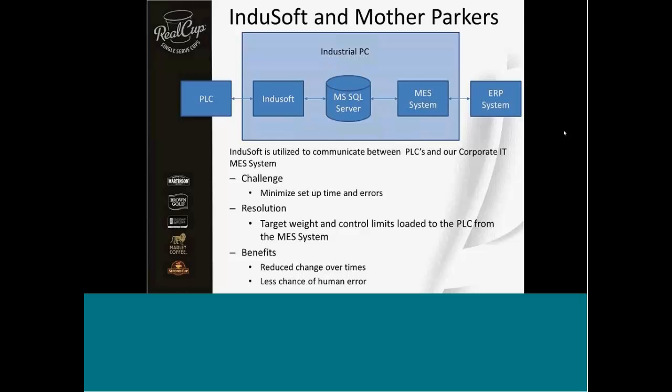And so in this scenario here, InduSoft is communicating with the PLCs. And then on the industrial PC, we have a Microsoft SQL Server. InduSoft will write data to our SQL Server. Our MES system will read data from that SQL Server and then communicate it to the ERP system. And then likewise, our ERP system can flow data to the MES, over to the SQL Server. InduSoft reads it from the SQL Server and then pushes it to the PLC.